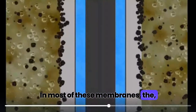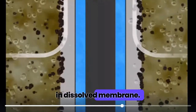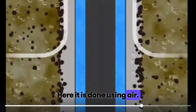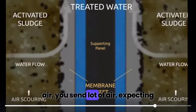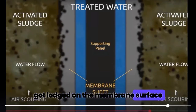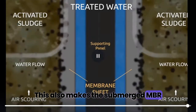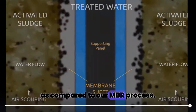In most of these membranes, the backwash is not very strong. Unlike an external UF membrane, in submerged membranes, the backwash is not done with external water. Here it is done using air. You just reverse the cycle, you stop the pump, and then you flush a lot of air. You send a lot of air, expecting that the impurities that have got lodged on the membrane surface are washed away because of air velocity. Right. This also makes the submerged MBR process a little bit more inefficient as compared to our MBR process.